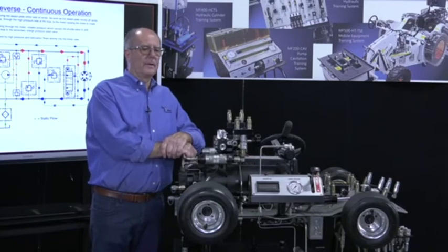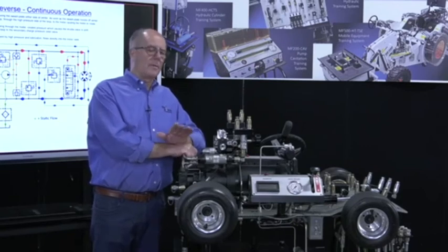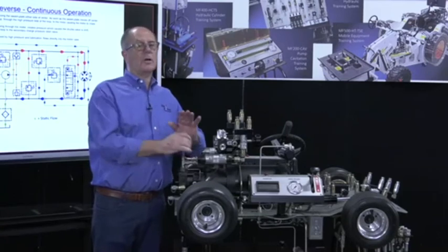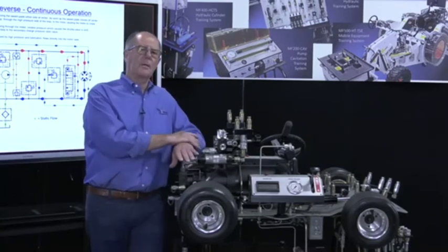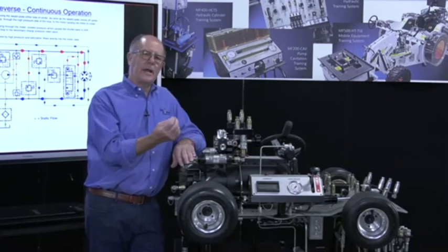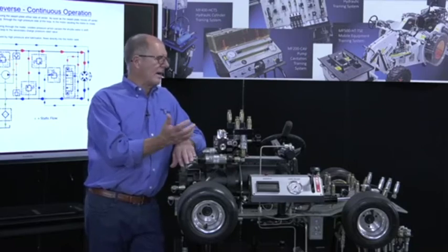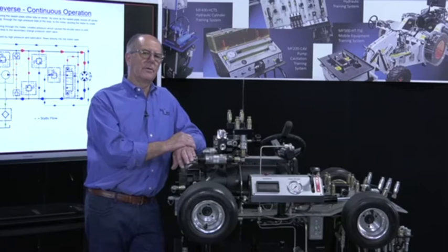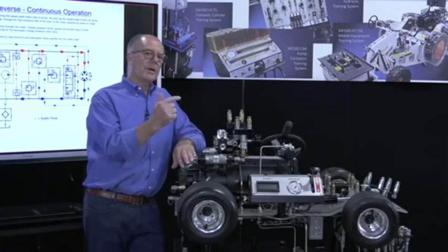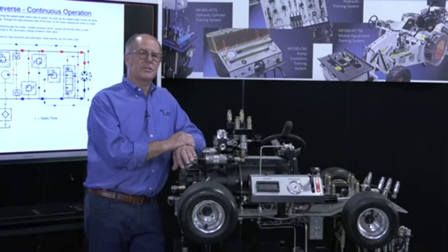In other words, if I blow a hydraulic pump on a catastrophic failure, not a normal wear failure, catastrophic failure, why would you ever put the closed loop hoses back? I'm not talking about replacing the case drain lines. I'm talking about flexible lines, not steel lines right now. Why would you ever put them back? Because if you've had fragmentation inside your pump and you've broken bearings or broken pistons, which are as hard as glass, why wouldn't one of those pieces go on and get stuck in the side of a piece of hose? It just deflected off something coming around a corner. One piece, that's all you need. You put a new pump and a new motor on there and you fire it up, and that piece dislodges as you have pressure spikes in your system, and it goes through, and it's done again.